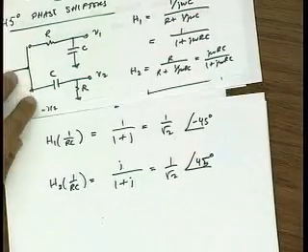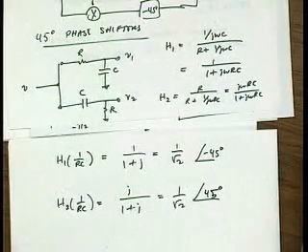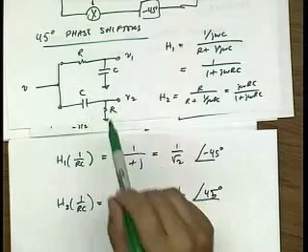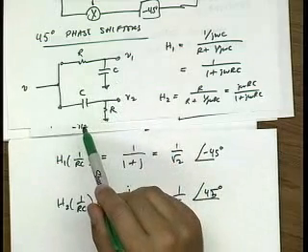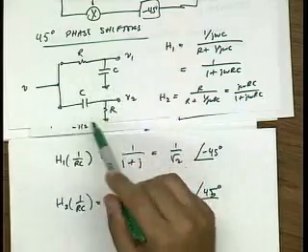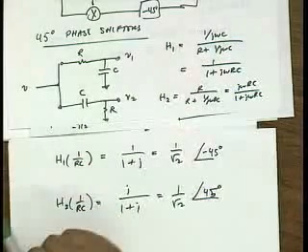Okay. Question, Kevin? Yeah, so typically are R and C going to be tunable? You have a good point. As we've drawn it, this only works for a single frequency, so it would only actually work for a narrowband signal. If you want to make a broadband version of this, it's basically a polyphase filter. You can do a multi-section version of this, and you get more broadband capability.